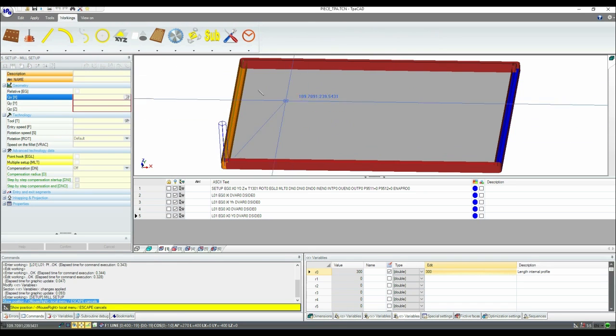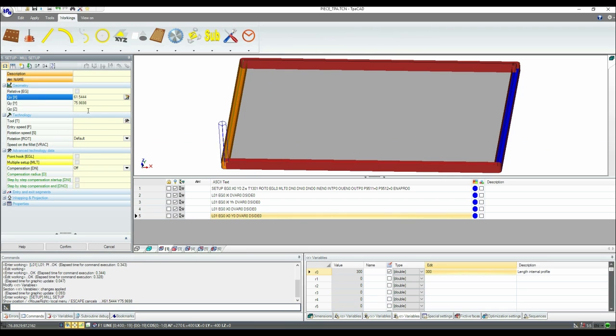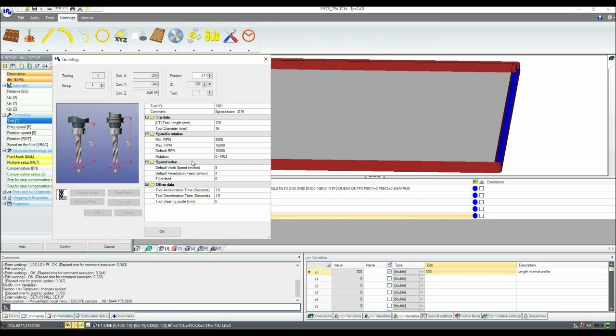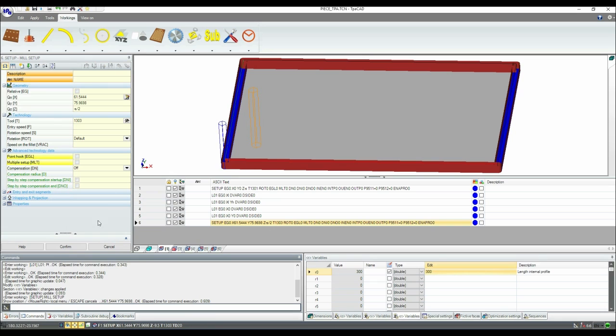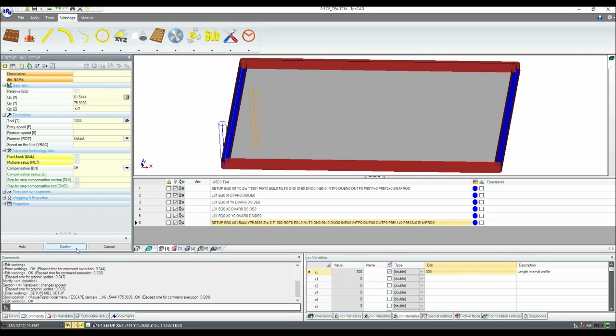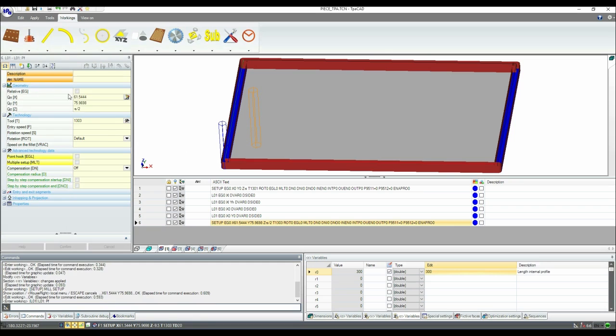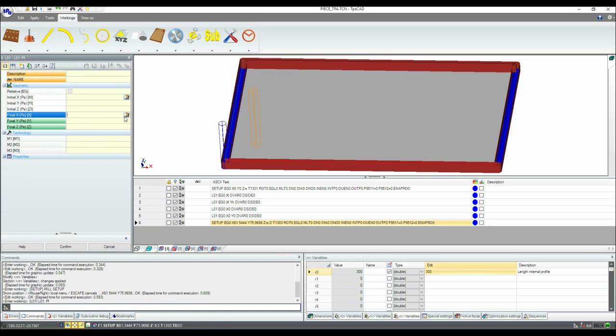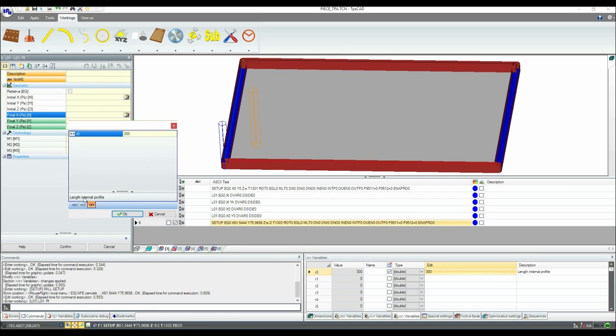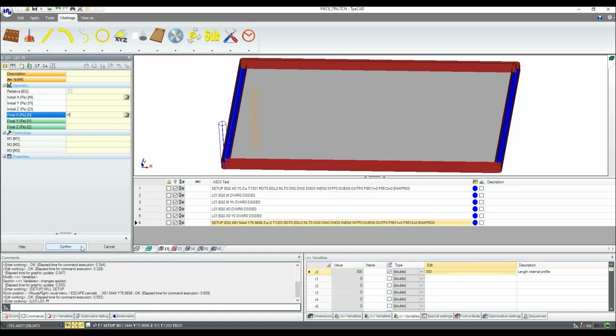I can take directly the point on the preview, always put minus s and half of the thickness, choose for example another tool, then do another rectangle but using the R variable. With the right click on the mouse I can take the list of variable, see the description of it and insert directly. Okay.